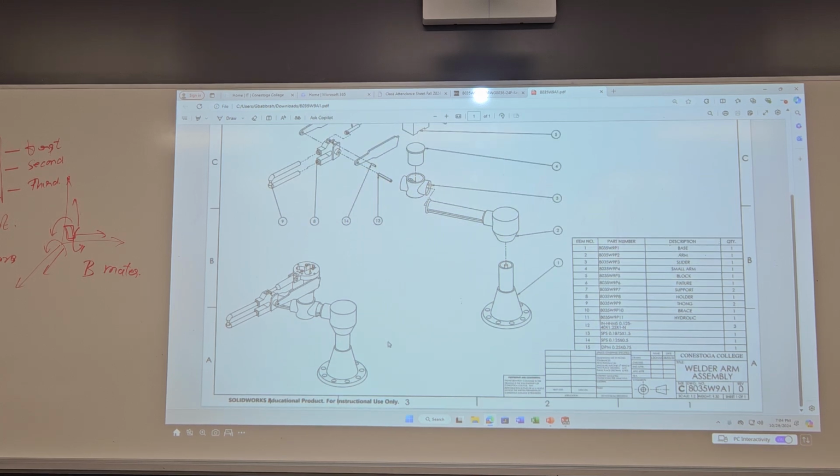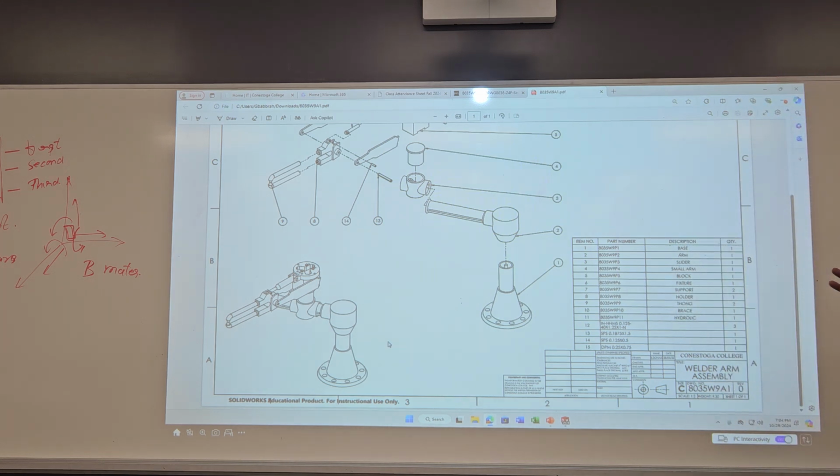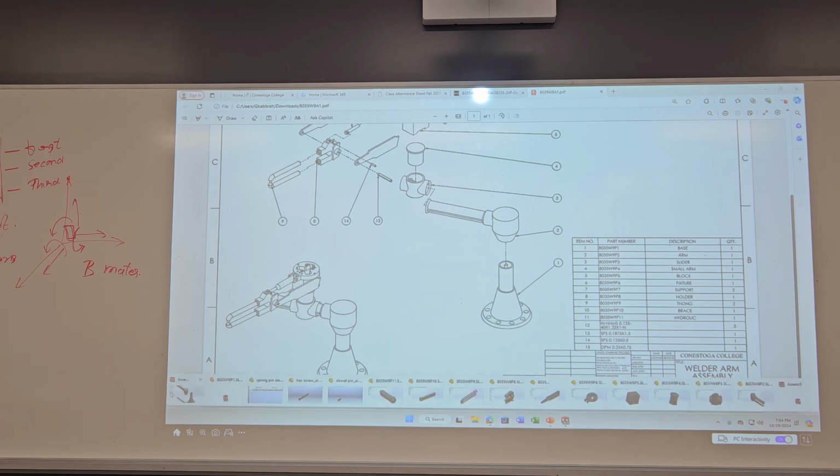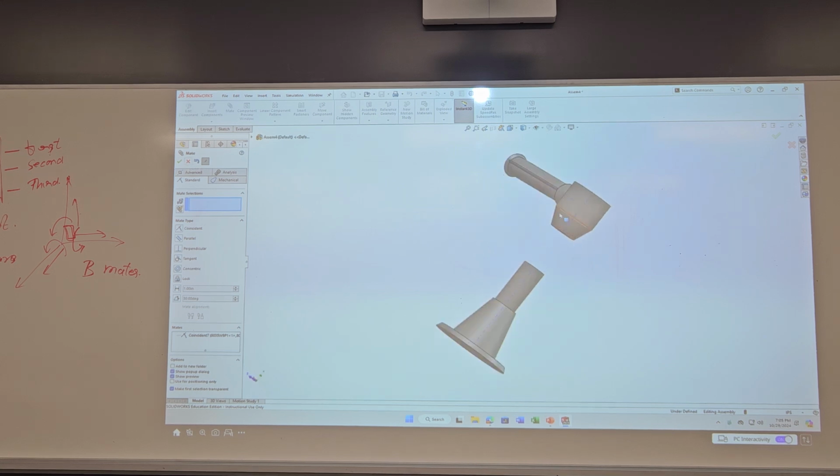Okay, now, everyone have that axis mated? Everyone good or not yet? Is the axis visible? No? Click on the eye and make them visible. So right there under this eye, here's your temporary axis. Click on it. Then you go into mates, select this axis, and say coincident.